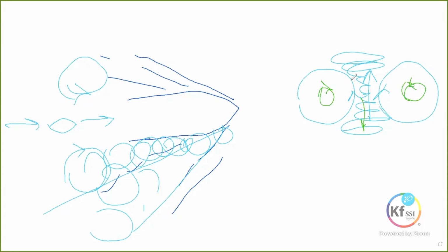And I discovered also in my travels in the last week or so that the human body has an equivalent in electrical terms. They say that the human body, in terms of electronic components, is equal to a 100 picofarad capacitor in series with a 1.5 kilo ohm resistor. In other words, a 1500 ohm resistor. So a 100 picofarad capacitor plus a 1500 ohm resistor in series is the effect of our human body in a circuit, in a way.